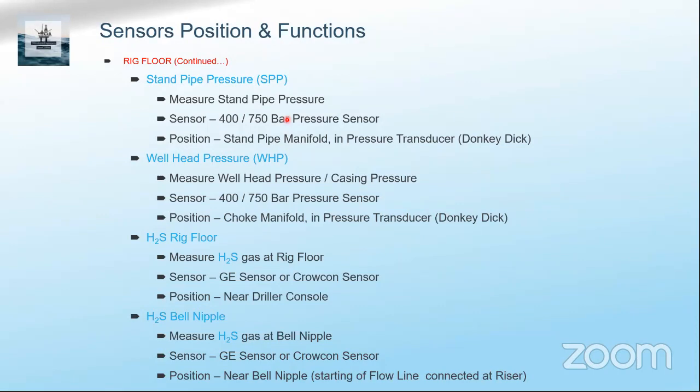The company man has to see it himself to be satisfied, and the geologist also has to make sure everything is correct. Once it is calibrated, make sure it is the same as the rig floor, then you can rely on it. Then all the plots and charts will be valid and the values will be useful. So it is very important to make sure that at the start of the operation, the mud loggers' calibration is correct for all the sensors, including the gas panels. Then you can have safe and reliable, meaningful charts.